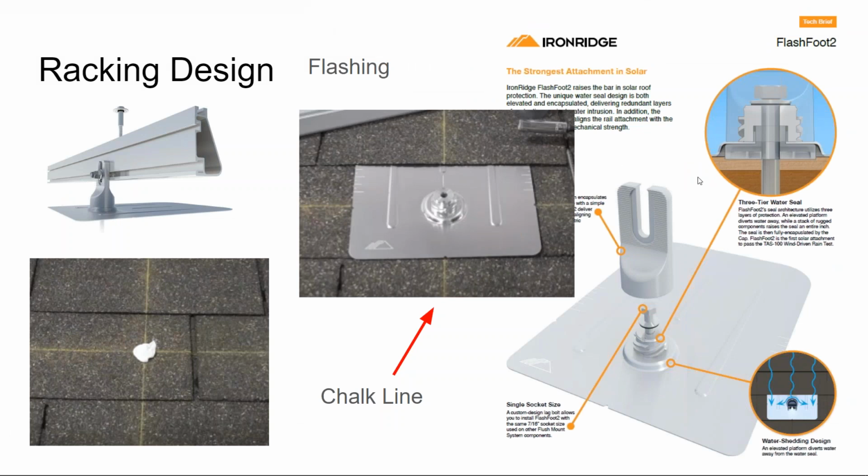When you're installing solar, one of the first things you do is get up on the rooftop and identify where the rafters are. The best way to identify where the rafters are is to use a $1,000 scanner, a $1,000 stud finder. And it's tricky. The shingles are not flat surfaces, so you have to slide a piece of thick construction paper underneath the shingle to give yourself a flat surface. So even using the $1,000 way, it doesn't work out well. So most installers will just hammer the rooftop and do it by sound.